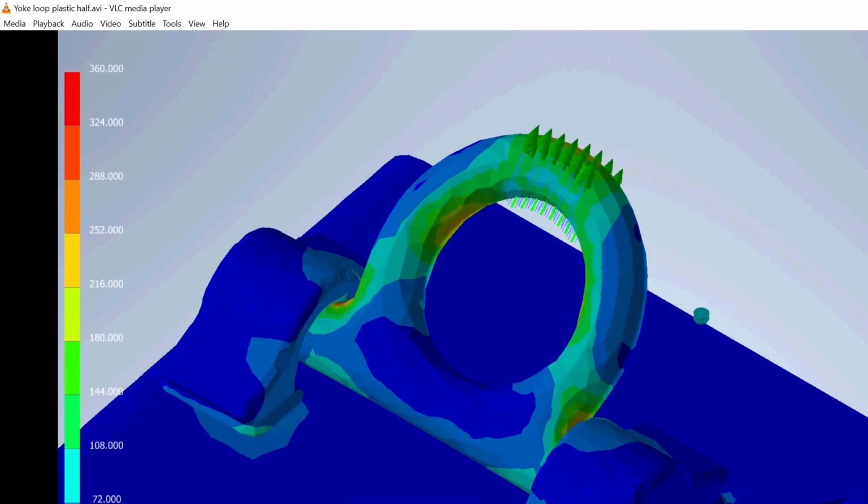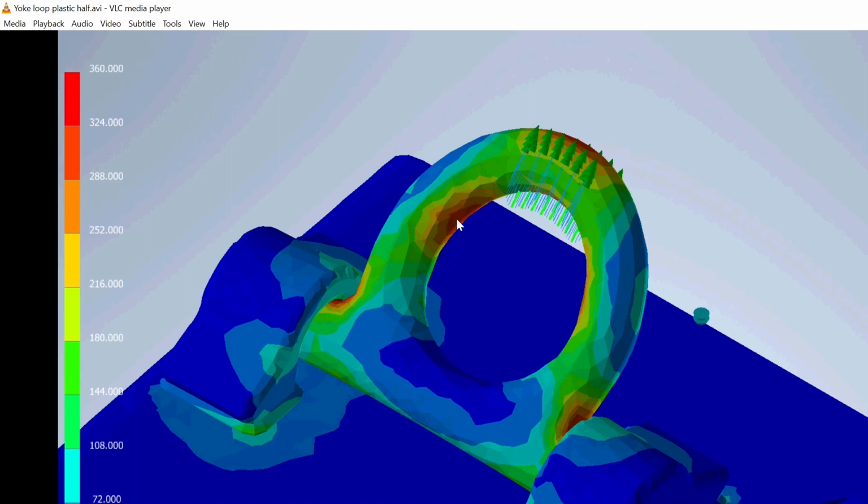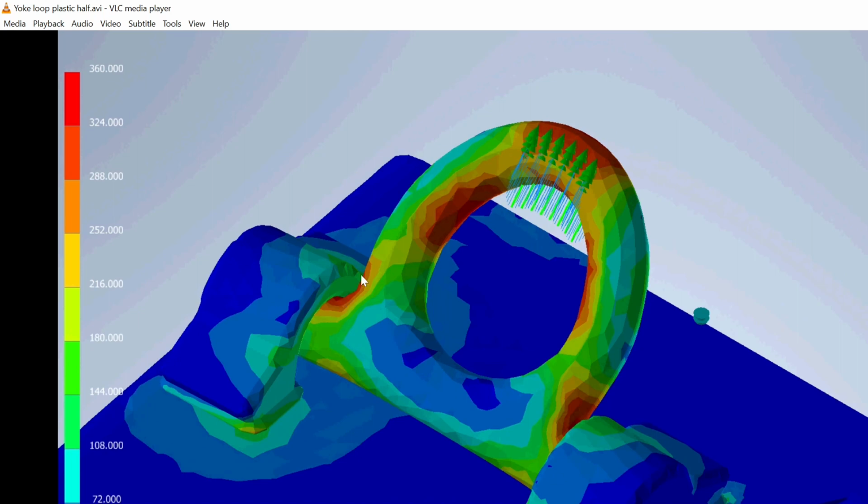So the interesting thing about this simulation type is that you can see the elastic part continues until approximately here where the first red one shows up. That's the plastic yielding inducing, and so technically without any permanent deformations it will hold about half the load, and that could be cyclic loading safe as well, and the welds are completely safe and everything is fine.